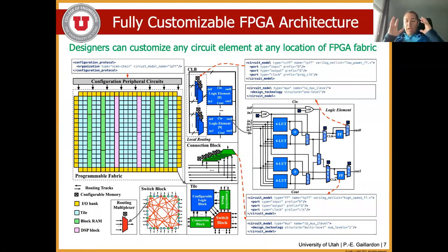So how do we model an FPGA architecture? Well, the whole point here is that we want to be able to model the architecture and its circuit components. And we do that using a high-level XML language. This XML language was not invented by us. We are using what VPR introduced a long time ago, Vaughn Betz from the University of Toronto. It is a very well-known way of modeling FPGA architectures, very well used and mastered in the FPGA field. And so we just augmented that rather than going with a different route.